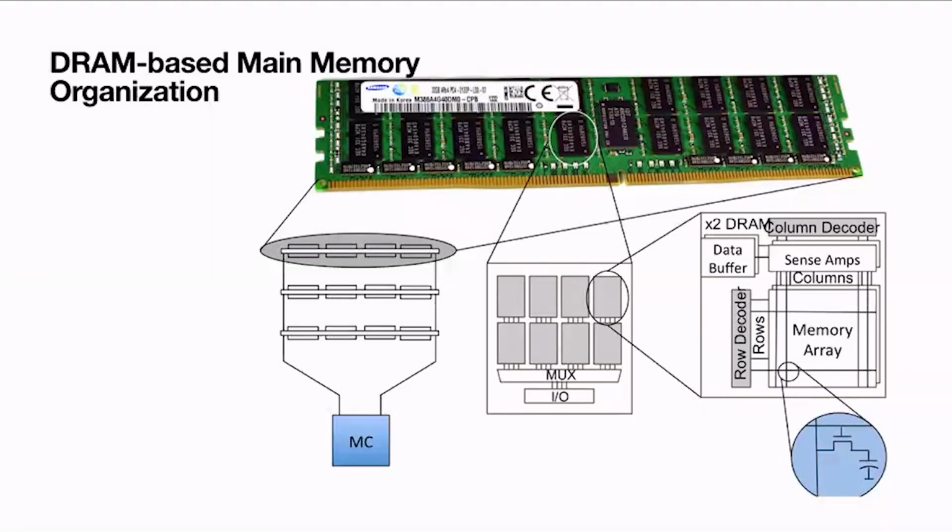So here the DIMM is a passive device which cannot do anything on its own, and it needs to be receiving some signals, and the signals will be sent by the memory controller. So effectively, the memory controller is the brain here, which is going to say what needs to be done at what time. And the DIMM is just simply implementing those functions. That's it.